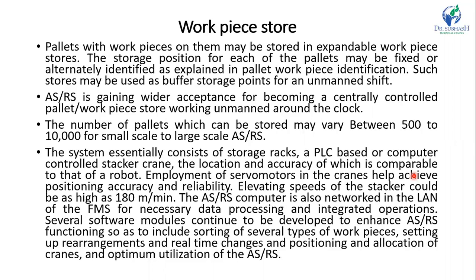So the system essentially consists of storage racks, a PLC based or computer controlled stacker crane, the location accuracy of which is comparable to that of a robot. So employment of a servo motor in the crane helps to achieve positioning accuracy and reliability. So elevating speed of the stacker could be as high as 180 meters per minute.